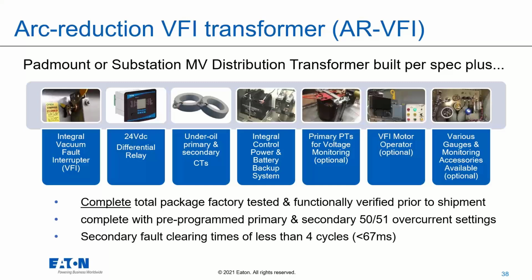We have also an incorporated differential relay there. The differential relay really just provides the inputs for the primary and the secondary CTs. So that gives us the instantaneous and the time over current, or the 50-51 protection on both the primary and secondary side. We also have included the primary and the secondary CTs integrated into the tank under oil. And along with that, we also have an integral control power and battery backup system.